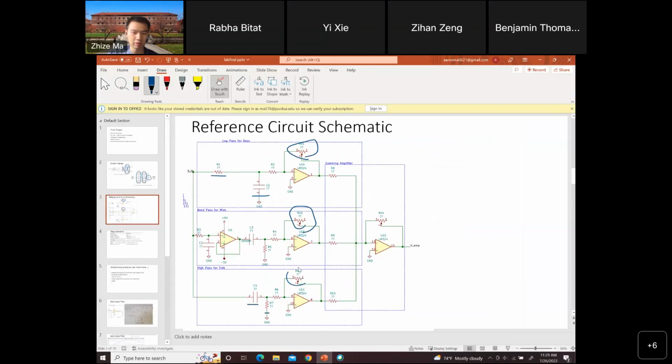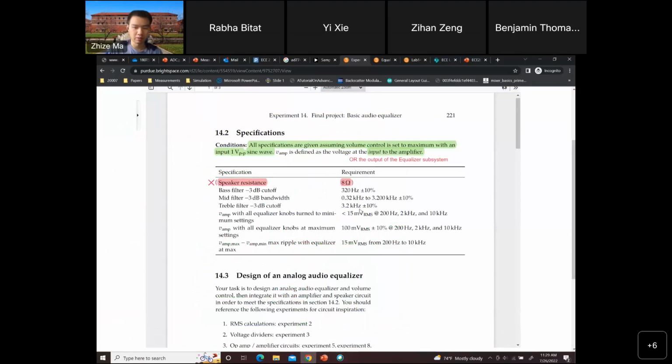And what you're going to use is a potentiometer. Okay, so when the knobs are set at maximum, this resistor will be a 10K ohm resistor. If you remember, the maximum resistance of the potentiometer is 10K. And when this is at minimum, that means your potentiometer will be at 0 ohm.